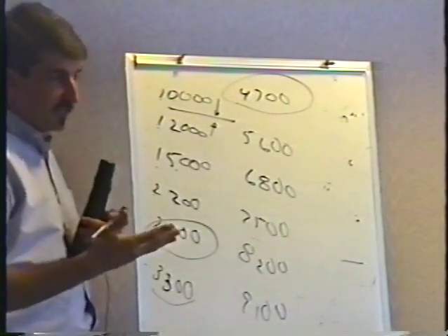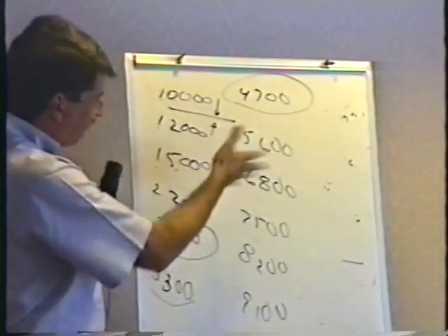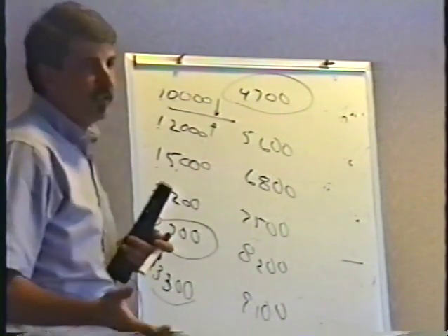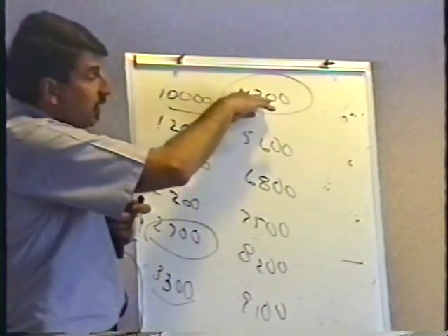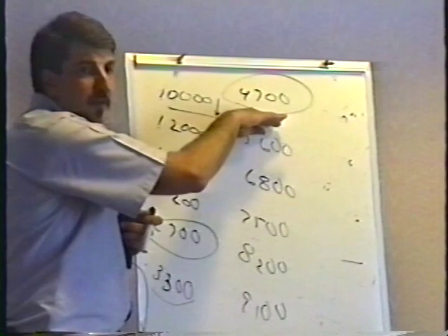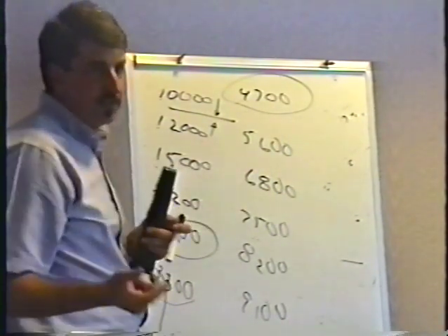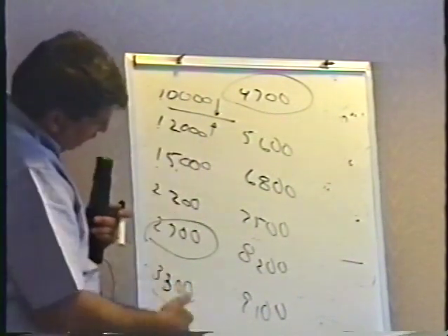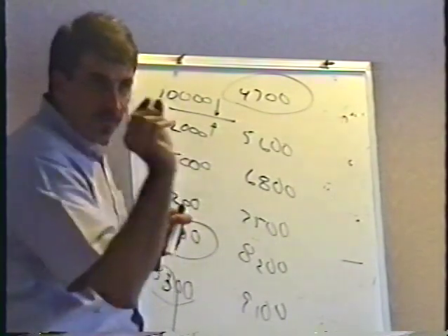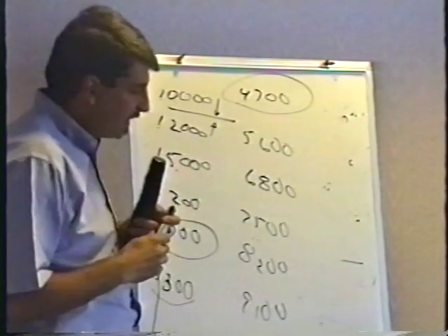You know, if somebody says, I've got a resistor that's 5,000 ohms, bullshit. You might have a 4,700 ohm resistor, or a 5,600, but you probably don't have a 5,000. They really just don't make them. They make them, but they'd be like precision resistors that we just wouldn't use. So you see the same maybe dozen first two color combinations over and over and over again, and the only thing that changes is the multiplier.